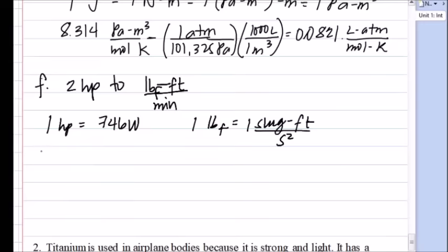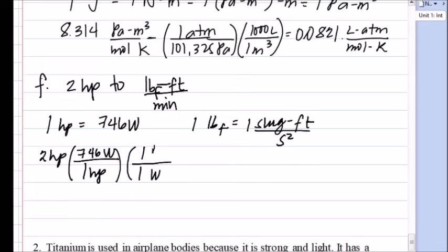So now, let's convert yung 2 horsepower sa watts. We can have 746 watts per horsepower. Maka-cancel po yung HP dyan. And then yung watts, as you all know, that is joules per second. Yung joules naman is Newton meter. So, 1 watt is maging 1 Newton meter per second.